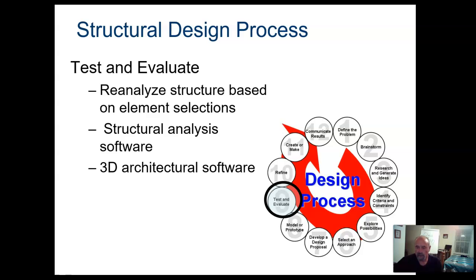For example, assume that you choose joists that weigh 20 pounds per foot for the preliminary analysis. However, the preliminary member did not provide adequate strength to carry the applied loads. You therefore had to change your selection, and you choose a member that weighs 25 pounds per foot. The increased weight will affect the design, and the member should be reanalyzed to make sure it can carry the additional weight.